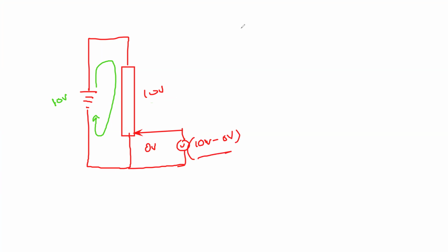But if I'm using a variable resistor as a rheostat, I will draw it in the same manner so you will have an idea how it works. We use one fixed end and one variable end, the sliding contact, and it is connected to a supply. Then the component is connected.